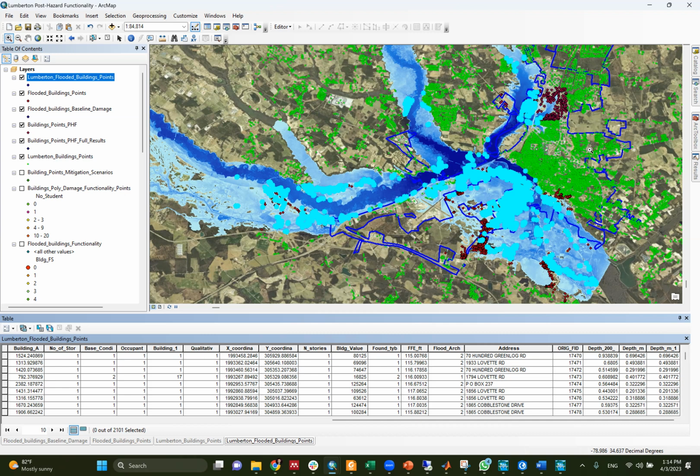For example, we have the first-floor elevation of each building. Let's assume this is the slab and this is my building. Usually for a slab-on-grade foundation, this is the ground, and maybe there's a step or two. So the first-floor elevation is around 1 foot from the ground because there's the slab, one or two steps, and the flooring. Then this is the FFE, and this is the ground elevation, okay? 1 foot makes a difference when it comes to flood losses.